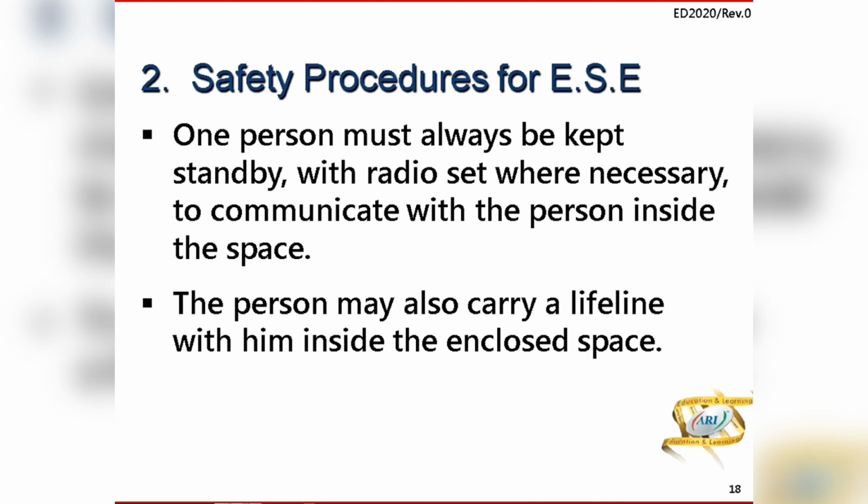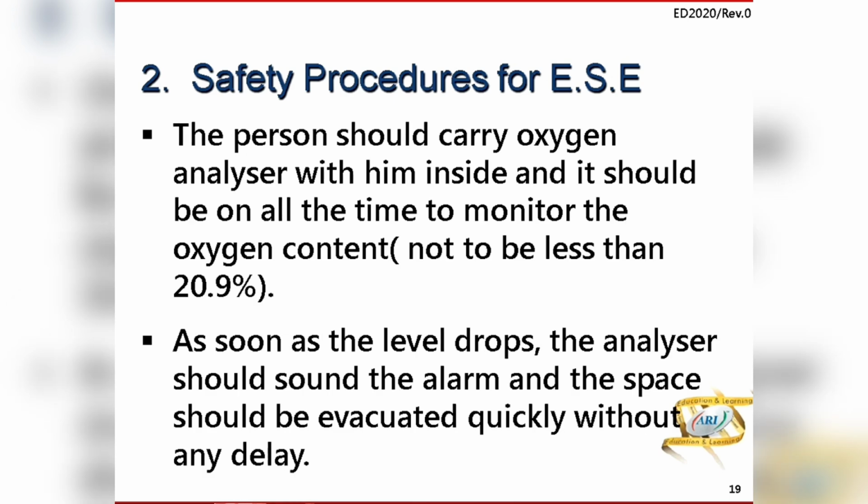One person must always be kept standby with a radio set, wherever necessary, to communicate with the person inside. The person may also carry a lifeline with him inside the enclosed space. The person should carry an O2 analyzer with him inside so that the oxygen can be monitored, which should be not less than 20.9% at any time.